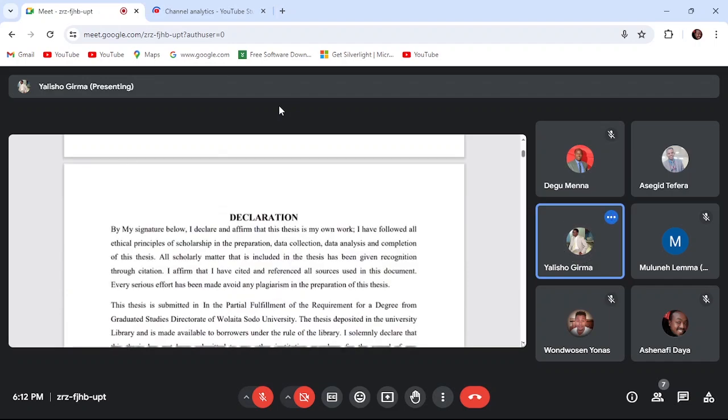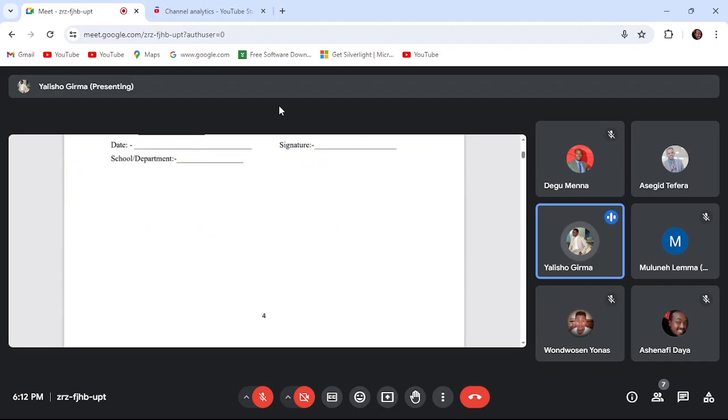Okay, so why have you chosen the FCTCR? This FCTCR is FACTS technology, and it is known that FCTCR can both consume and inject reactive power to the system. So the most important question for you: is there any capacitive load in the Wolaita Sodo distribution system?